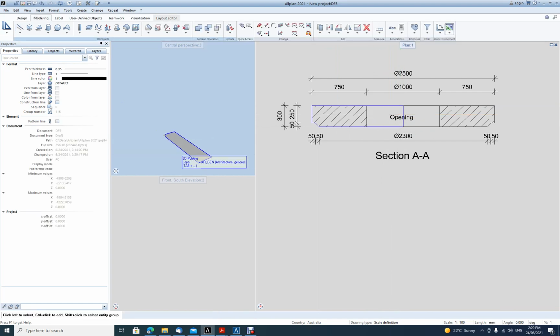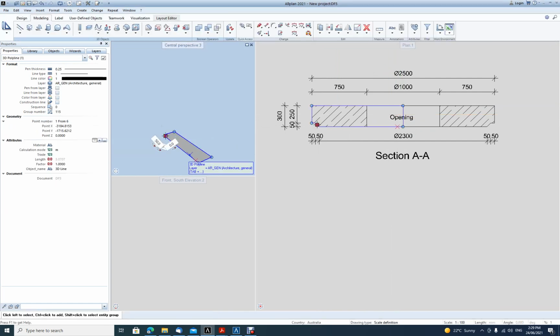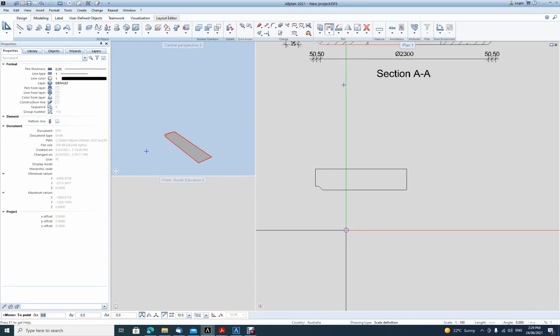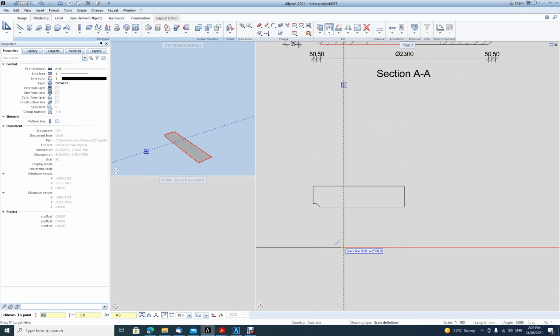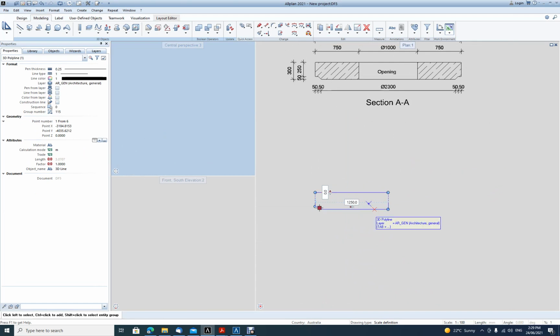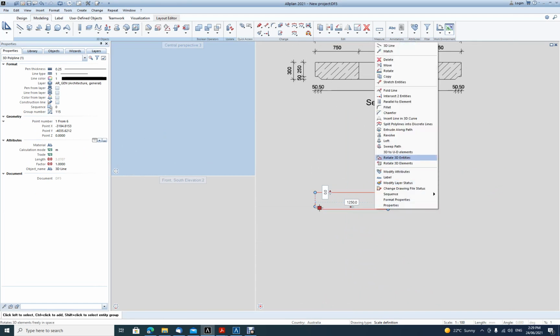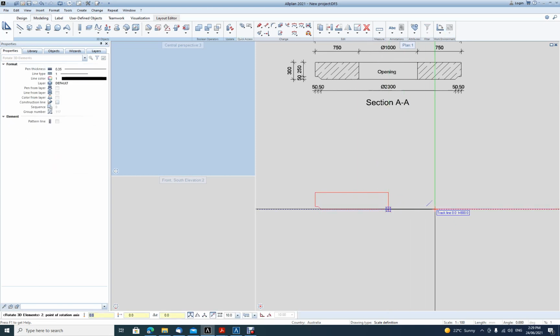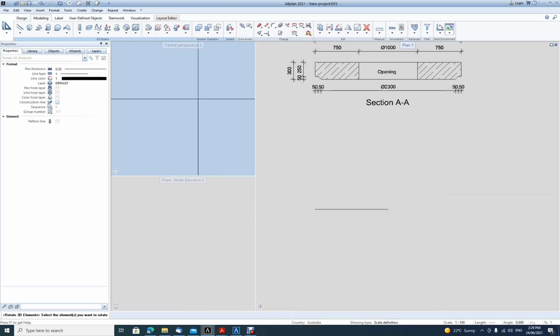As soon as I finished, you can already see, because it's a 3D line, it also can be presented in the animation window. So what I'm gonna do, I'm gonna move this 3D line away from my 2D drawing, and I'm going to rotate this 3D element. For the rotation, I'll just create an axis and I'll rotate it by 90 degrees. Now I can see my